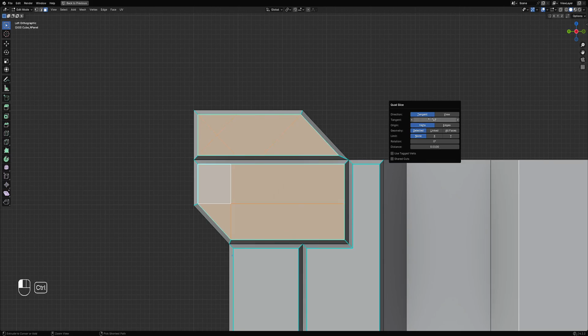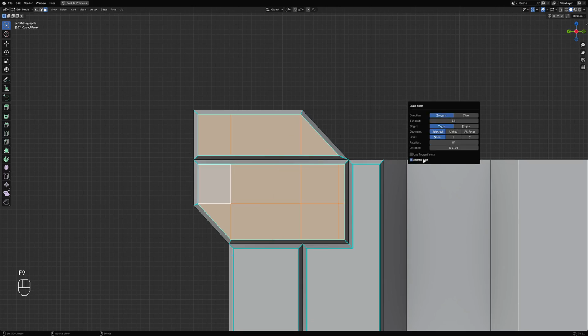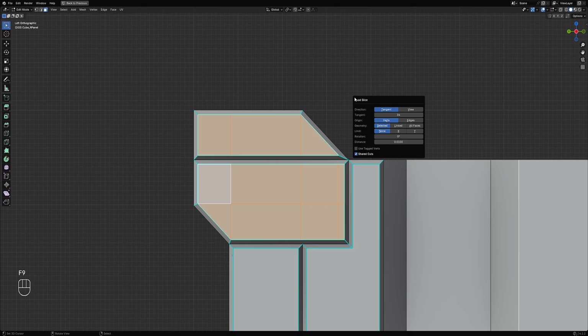I don't know why the cut is not doing its work. Anyway, we can use the view. It means that the selected faces can share cuts together. As you can see here, each face only cuts itself, but with shared cuts, the cuts between the two faces, there we go. So the points from each of the selected faces can now be shared globally.